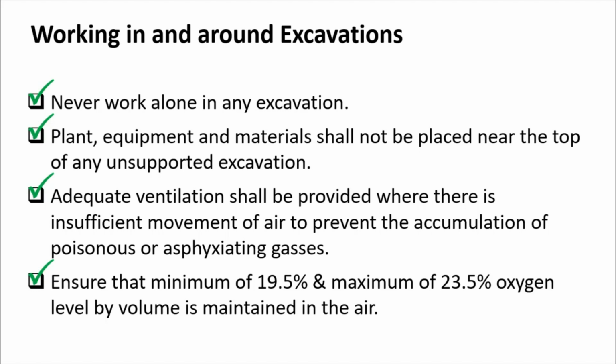So on that gas detector you can check the available oxygen in a particular space, to make sure that you are not below 19.5% or exceeding 23.5%. If you are below 19.5%, the people working inside the excavation will have difficulty breathing.